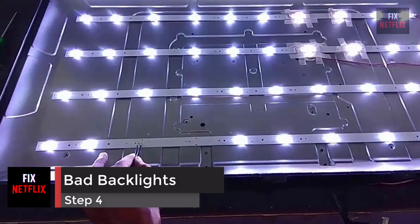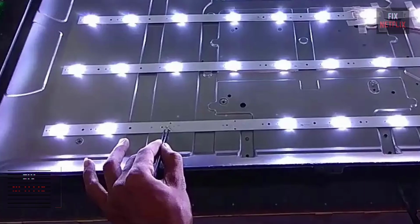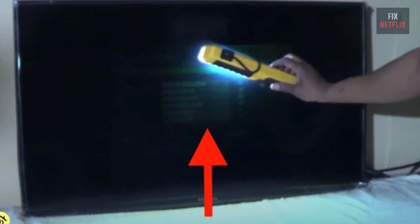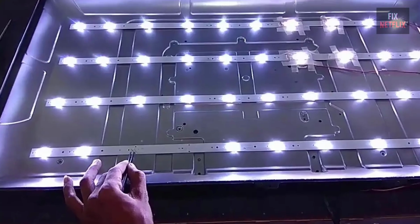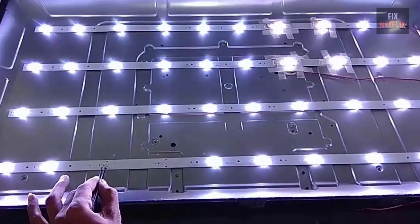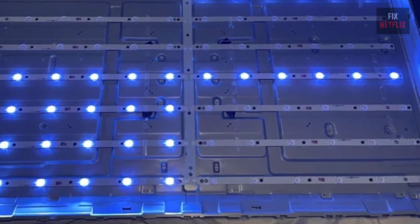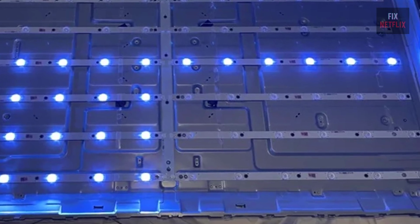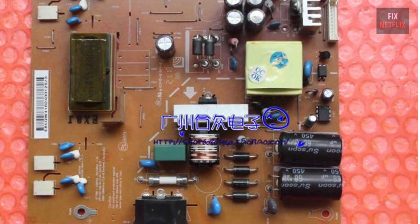Step 4. Bad backlights. This quick test will help you determine if the backlights on your TV have failed. Turn on the TV. Shine a bright flashlight at a slight angle to the screen. If you do see an image, this is a sign that the backlights have failed. The generation of the image means everything else is working properly. The TV will likely not give blink codes or any other trouble sign. You can replace backlights with aftermarket parts that are available. If you don't see an image, you need to determine if your power supply is bad.